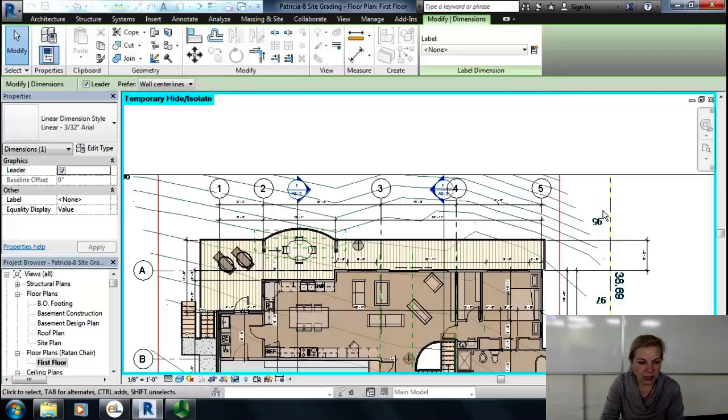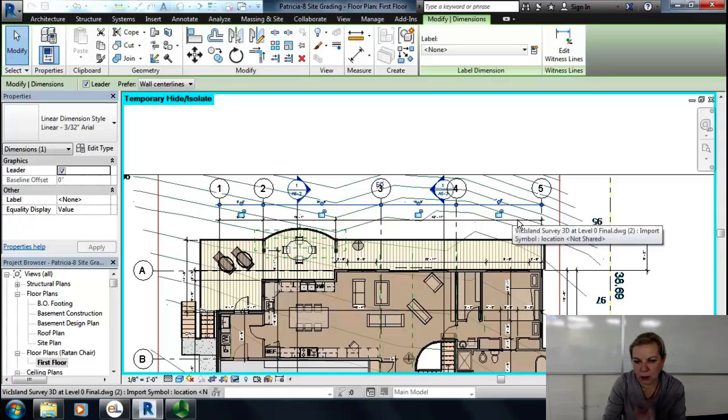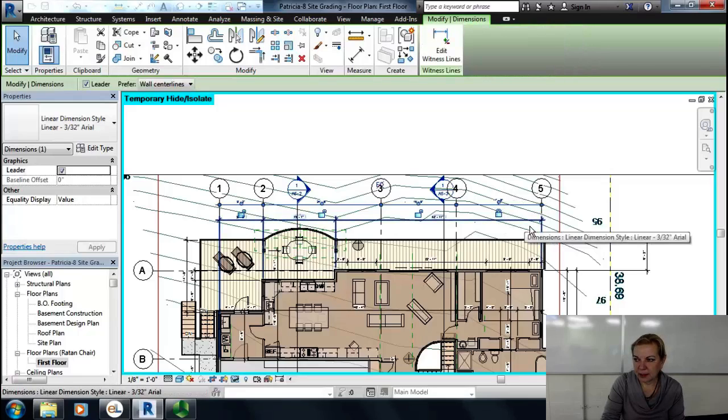And remove. Okay. So that's alteration number 2, because the first one was moving grips and moving the text, which is similar to AutoCAD. But if you have this selected, there are a couple of other things that you might want to use. If for whatever reason this center line 4 and 5 have to be locked, then lock it. If that's the grid line that cannot be altered by accident or by someone else, lock it.